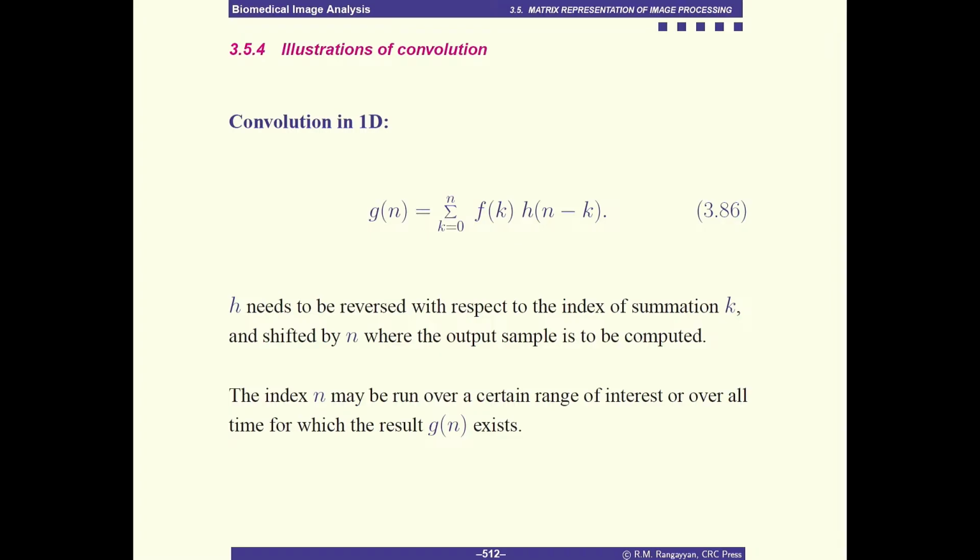Walsh-Hadamard functions have been used more for data compression and so on. Filtering is typically done using the Fourier transform because you have a better understanding of the frequency. Here you have sequency and it's a little harder to correlate sequency with the nature of noise. So I have not seen good examples of filtering using the Walsh-Hadamard transform. But I have read papers where it's used for data compression. What you do with the transform is up to you, whether ultrasound or any other image. How you filter depends on how you interpret those components.